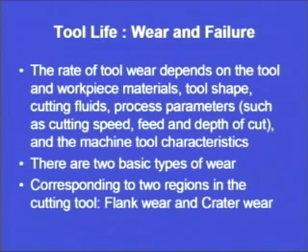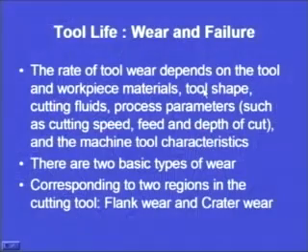If the machine tool is vibrating or has chatter, then the tool will also move, because the tool is mounted on a tool post which is mounted on the machine. So, if the machine is vibrating, then the tool post will vibrate and consequently the tool will vibrate and there will be excessive wear of the tool. So, the tool wear is dependent upon a number of parameters: the tool and the workpiece material, the tool shape, the cutting fluids, the process parameters and the machine tool characteristics. So, the tool wear will depend upon all these different parameters.